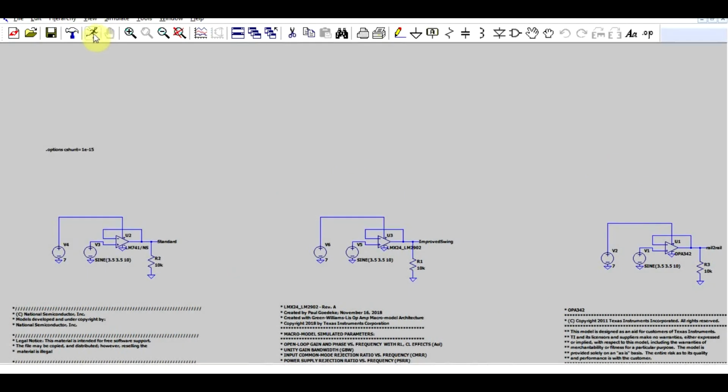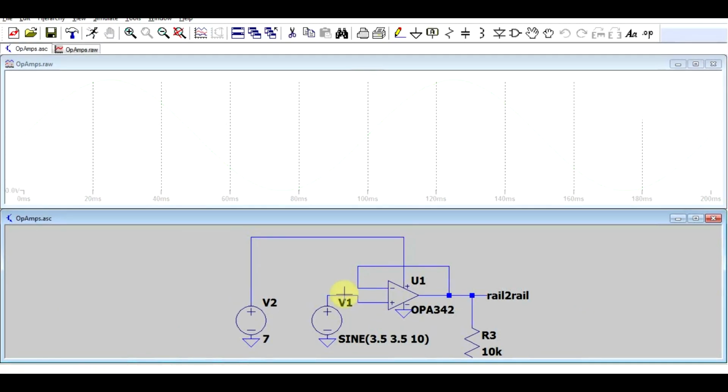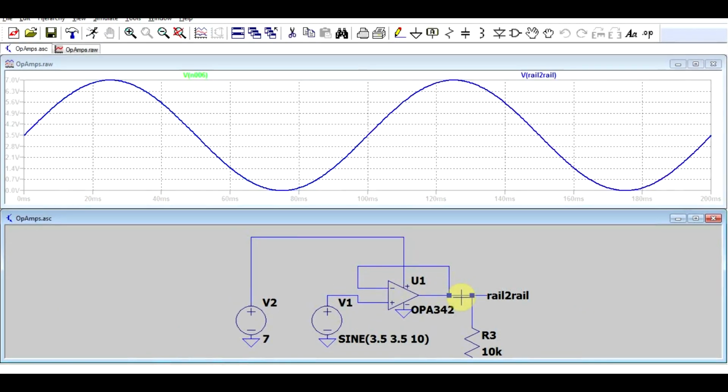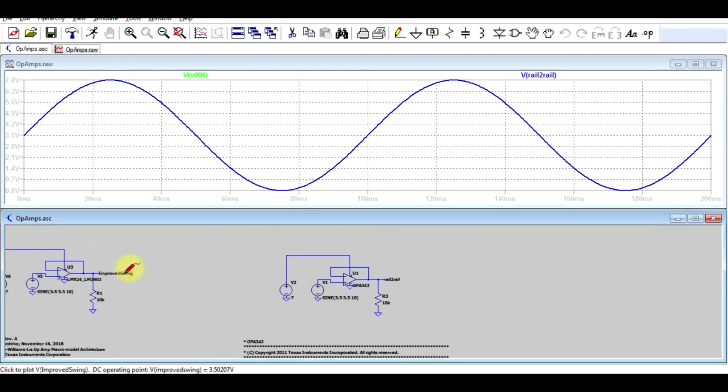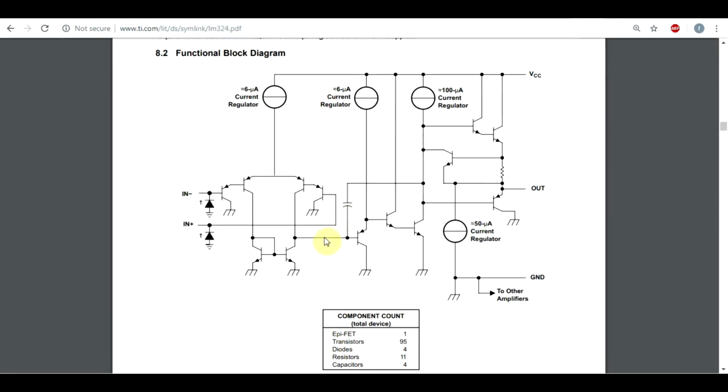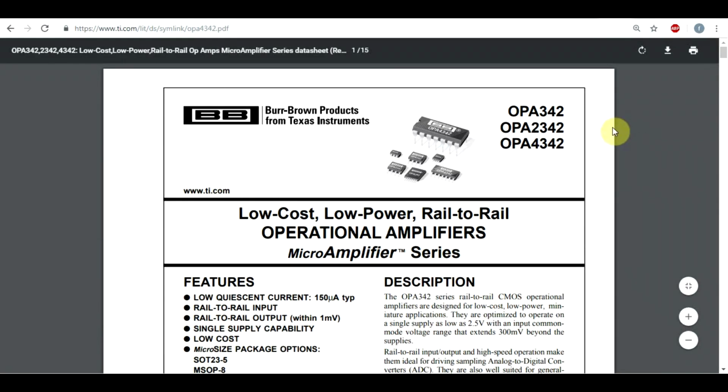In my initial simulation, I had one op-amp whose input was exactly the same as the output. So what's going on here? Why don't we have any limitations, neither on the top side, neither on the bottom side? I mean, we saw why we have limitations and how to improve them on one of the extremes, but not on both. Well, this is actually done by doing this sort of input stage twice. And we get to this op-amp, so there's many like it, but this is just one example, but this is part of a class of rail-to-rail op-amps.